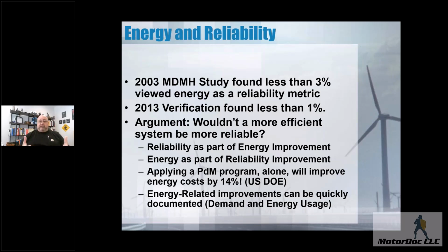I'm going out to a customer, we're heading out right after this for an on-site for the next 2 days, because we had been there a couple of years ago and we identified a lubrication issue with electrical signature analysis that was causing an increase in motor consumption by several kilowatts. It came out to be about $5,000 a year worth of energy, solved with a few squirts of grease. So they're calling us in because they're having other energy problems.